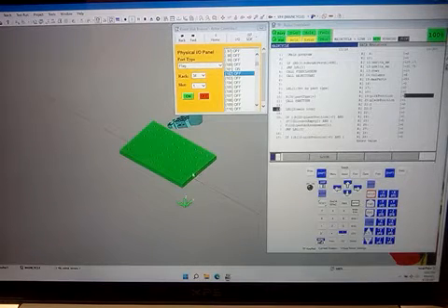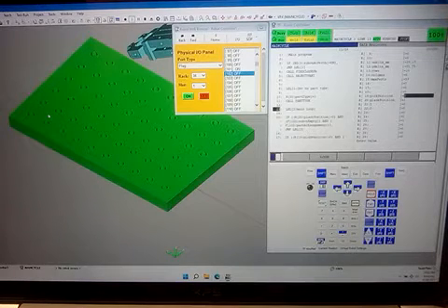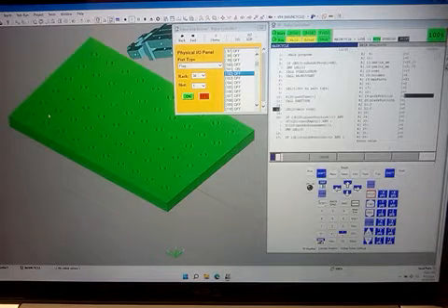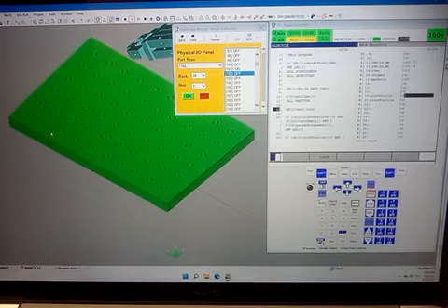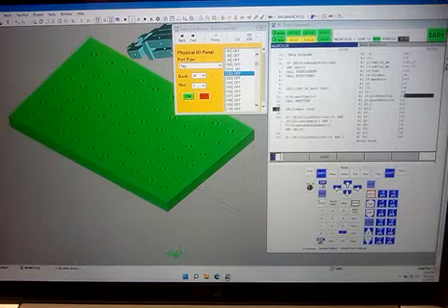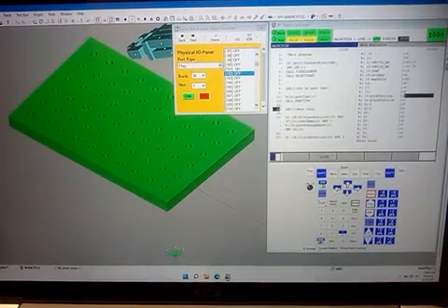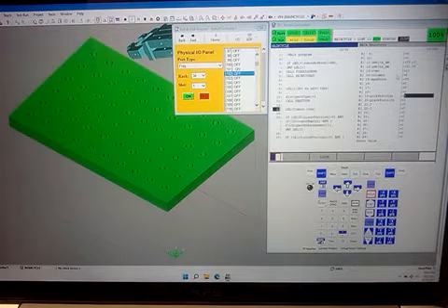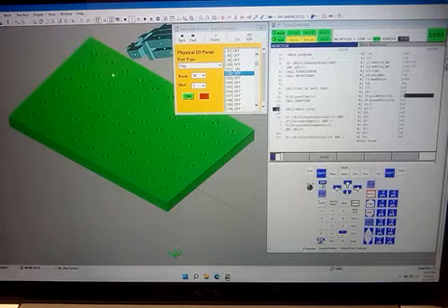But the change we're going to make is when I make the robot run different part sizes. So this is for a 13 millimeter size element. It's going to be running 3 more part types, different sizes, so the plate may look different, may have a different geometric arrangement, different hole sizes, and number of holes in X and Y. So the PLC is going to tell which part type is going to run, and all the grid distances are pre-stored using R registers. And then also the geometry of the plate.